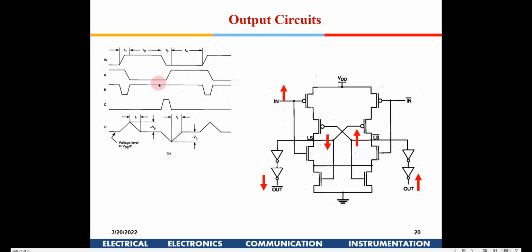Okay. Now this is the kind of signal which is received here. Now if you see here, this is a particular circuit on the receiving side. So you have these in and in bar. If the in signal goes high, you will find that it is again a cross coupled latch. So an increase in this signal will switch on this NMOS, and this voltage will drop, and that voltage drop will switch on this PMOS. So this will go high, and this feedback is given here. So this will be switched off, and that will enable further. So it is a positive feedback circuit.